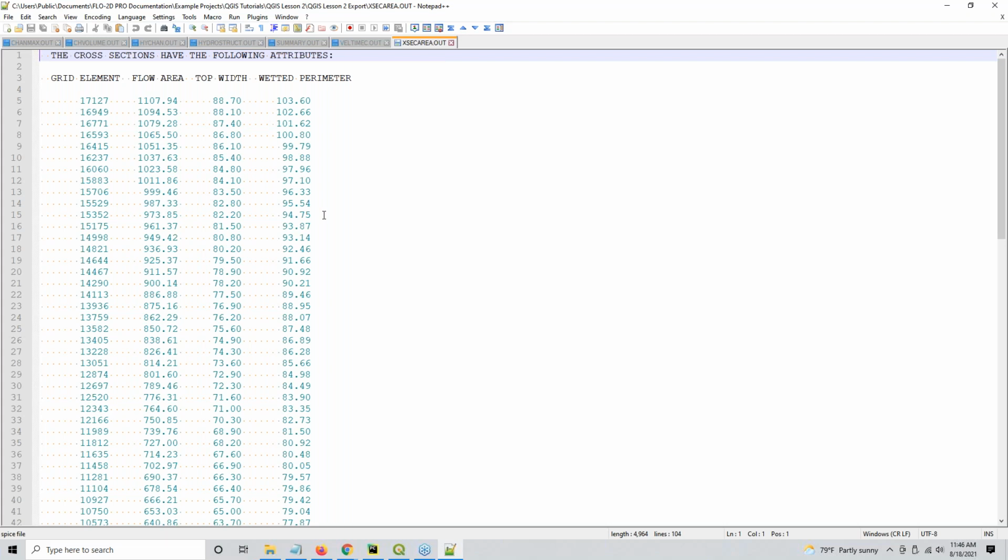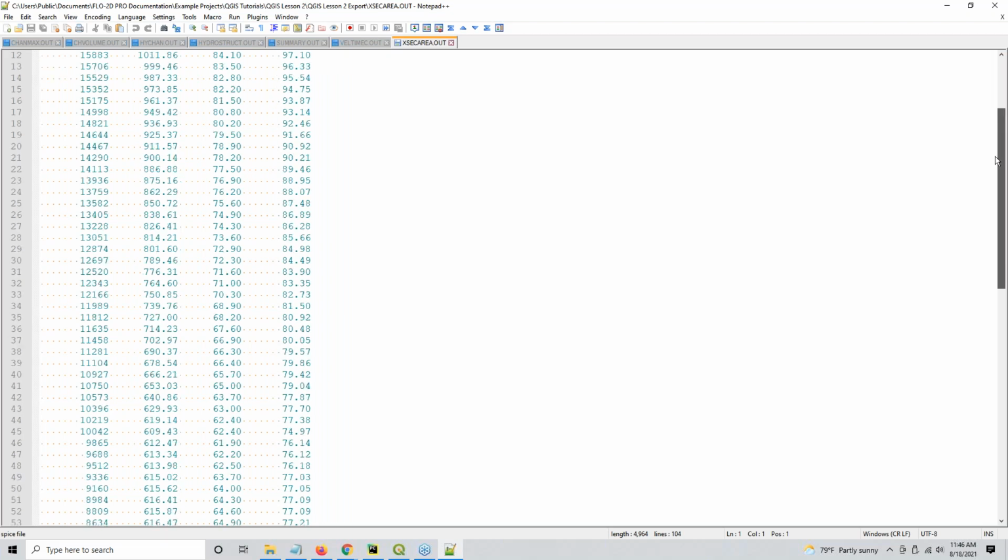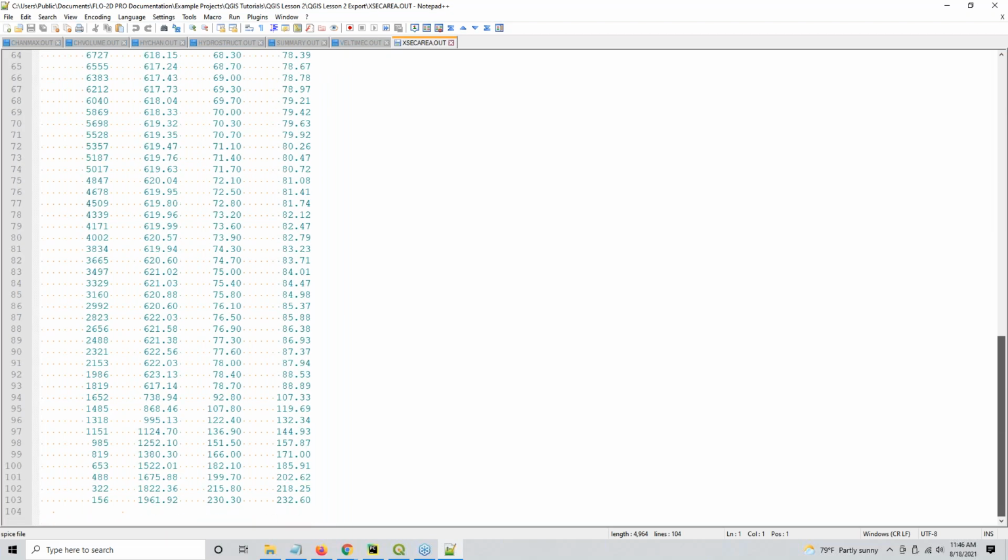So what are we looking for when we're doing a quick review of our channel? We want to see, is this channel working correctly? If you've set up your data file correctly, like we showed you in the first couple of lessons, then you should be confident that everything is working okay. What we're looking for when we scan through this data quickly is anomalies. Especially in exec area.out, what do I not want to see? I don't want to see anything blow up in these numbers.